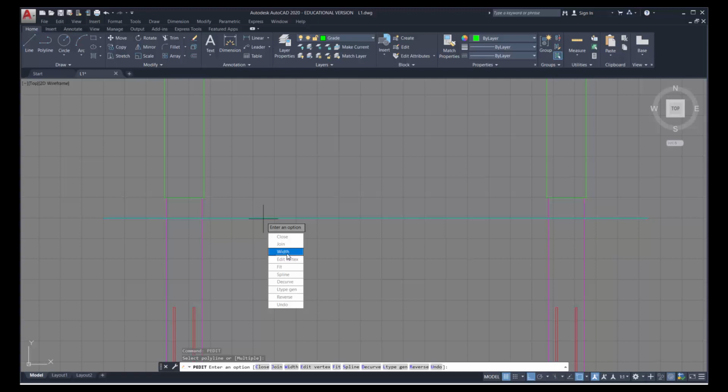So with this one, we're going to adjust the width to make it thicker. And here the width will be 0.5 or half an inch. And you can see right away on your screen that it has that effect. This is the better way to control line thickness than to actually go into the print menu and adjust the line settings. This will stay with the drawing, and it doesn't require an accommodating line set.